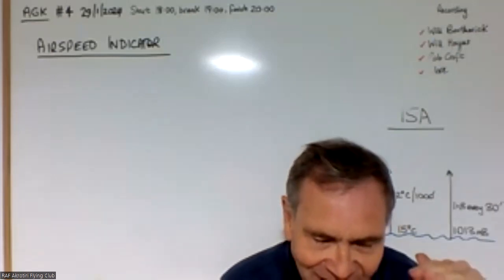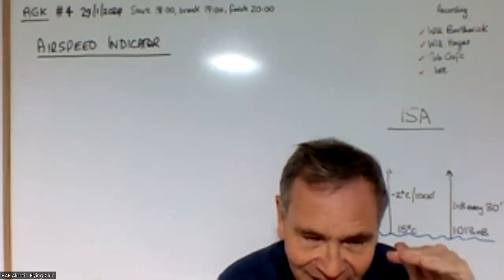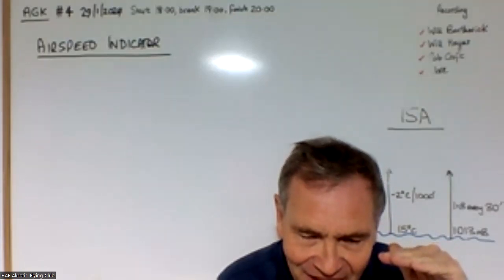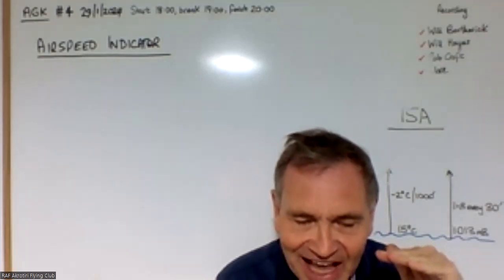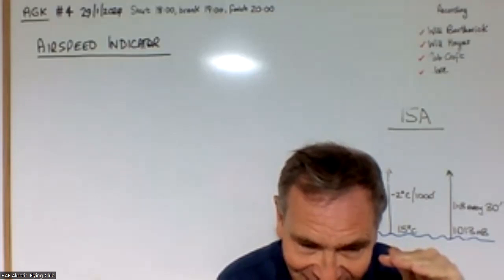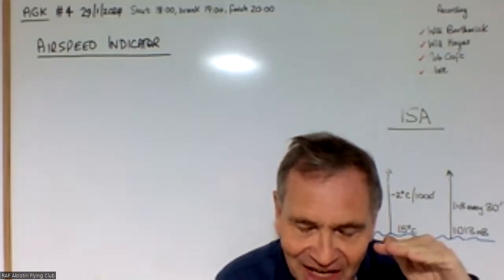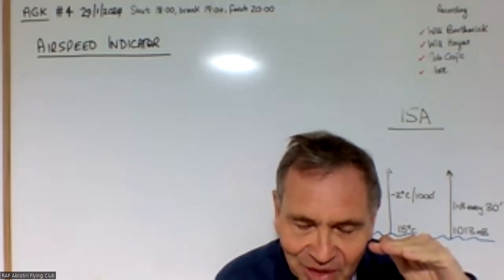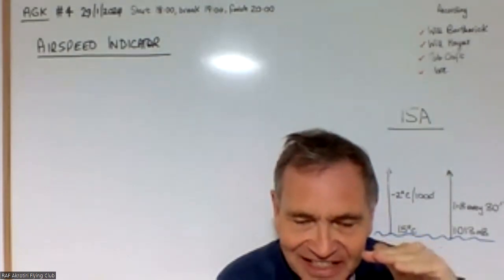Well, think about it. If you're descending, then the static pressure that should have been cancelling out isn't. So that means that the pressure that's in the back of the instrument is going to increase, isn't it?